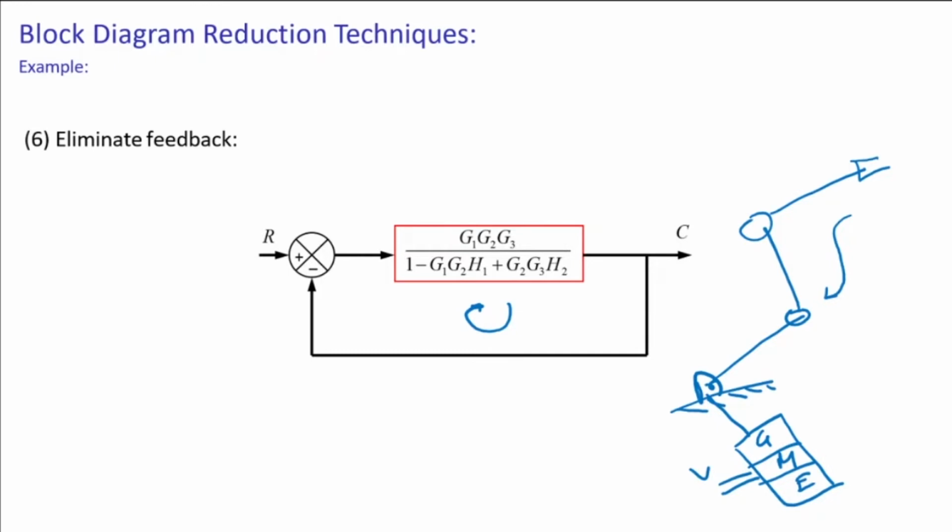But when the robot is moving, the velocities and accelerations are propagating. So if this link moves with a particular velocity, the second link is going to have its own velocity plus the velocity of the previous link, and this will start going forward. Similarly, if there is a force there, this force will come backwards. Because of this propagation, the motion of any of the links has an effect on the forward links. This is basically what we get from our dynamic equations. Now we know the dynamics will consist of inertia forces, Coriolis centrifugal force, and gravity forces.